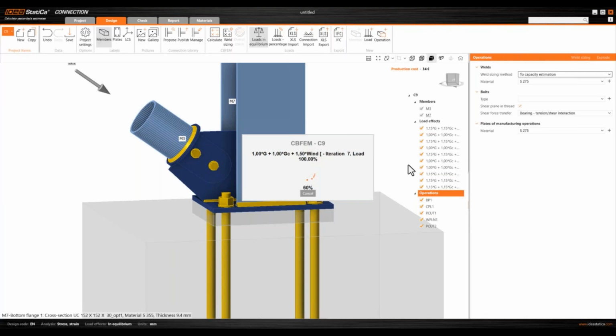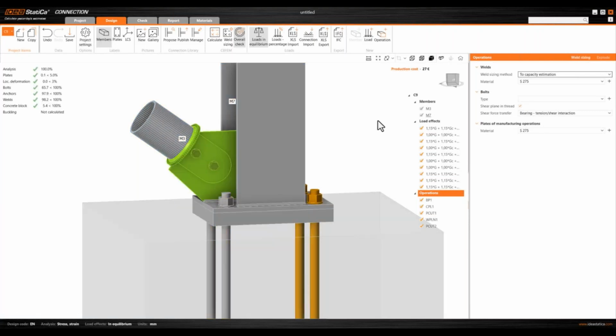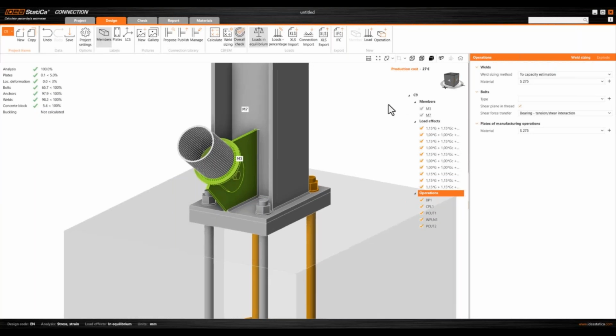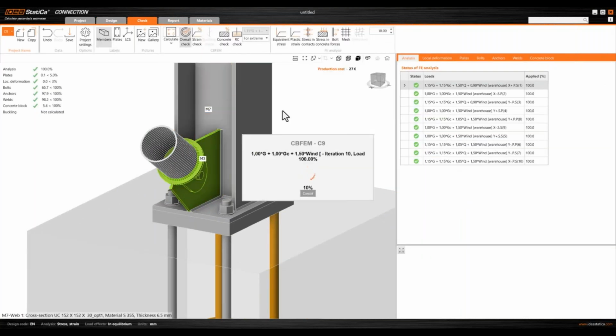And the reason we do that is because after this calculation is over, it will take the results and apply a machine learning model we have developed that will calculate every connection weld to its capacity. So let's wait a bit for this segment. And everything is okay. The configuration appears to be passing all checks, and please note that it's supported, the gusset is supported on 2 edges.